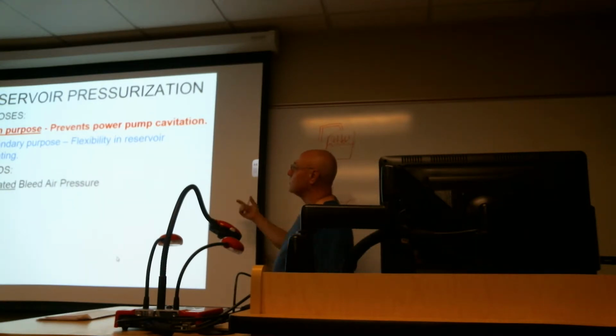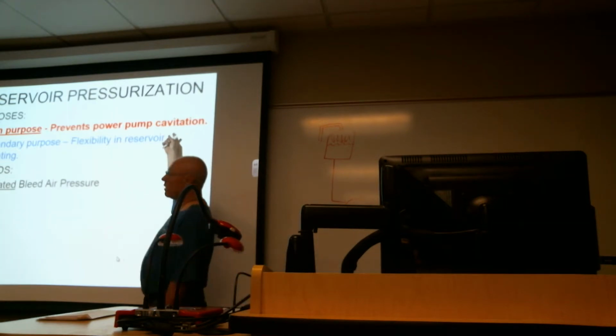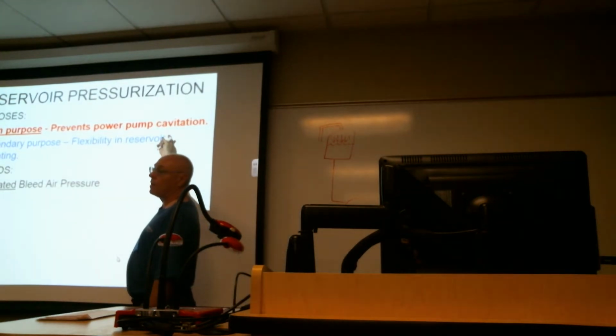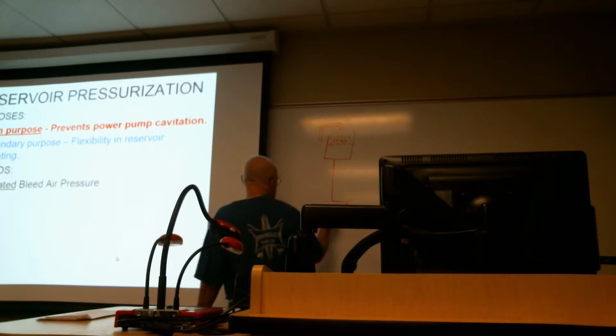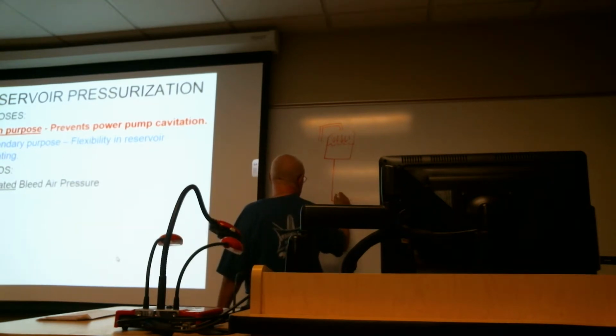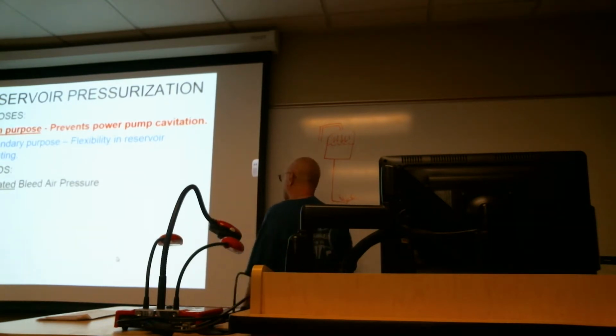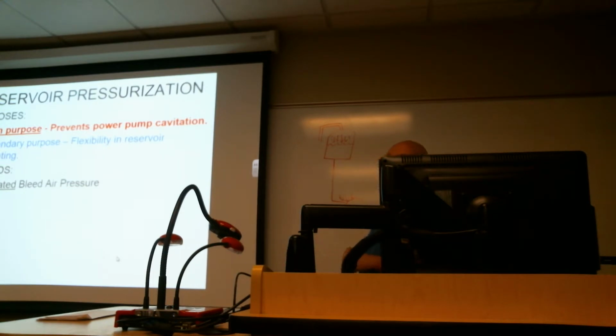So the primary purpose of pressurizing a reservoir is that it prevents the power pump from cavitating. I'm going to send you a video concerning power pump cavitation of hydraulic fluid, but it's especially damaging to the pump. The problem is you're building up voids in the liquid that are really a vaporized form of the hydraulic fluid.